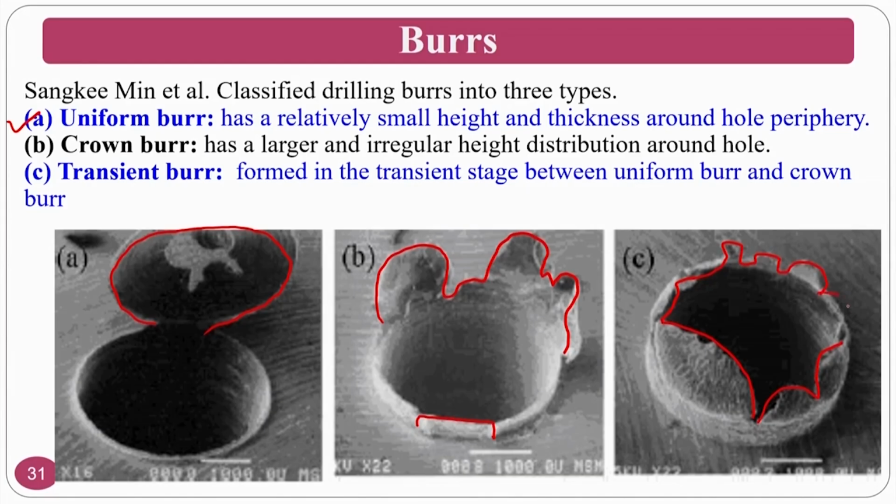These are the burrs that you generally see in a drilling process on the back side of the workpiece. If you are going to drill a through hole and you do not remove the chip which comes at the end properly, this will hamper the operators and the customers who are handling these particular components.